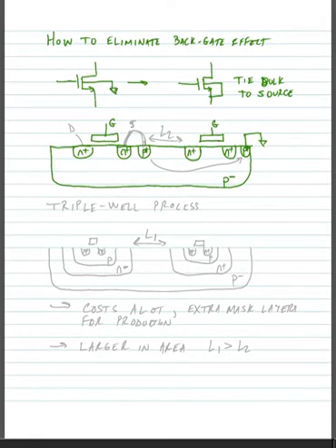So let's say that this is my drain of this transistor and this is my source, and I want to tie my source directly to the bulk connection, this P+ implant. Well, if I do that, because this P+ implant is at the same potential as this P+ implant, we're grounding the entire substrate, then that would mean that this transistor's source would be connected to ground no matter what I did. So I can't make that connection and still achieve, for instance, a common drain amplifier.